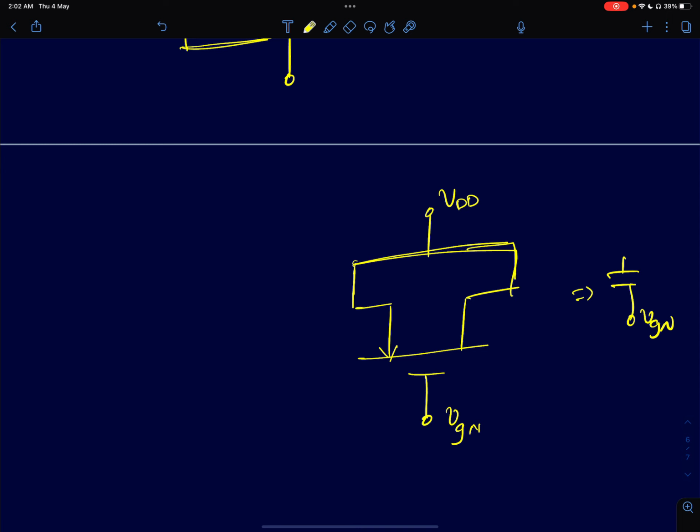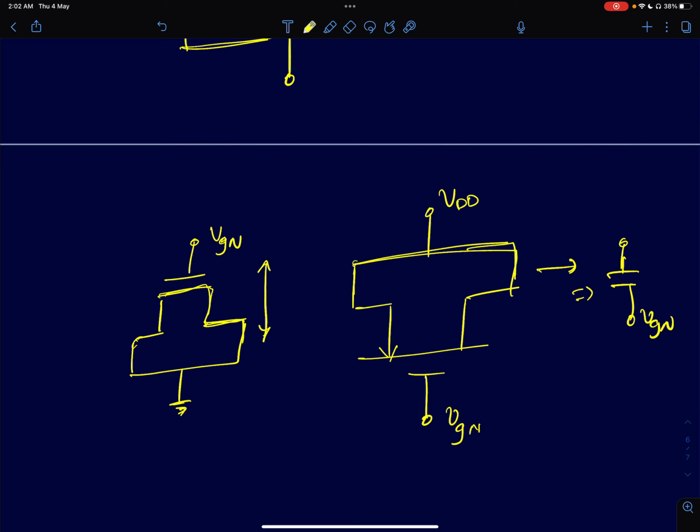So typically if you're realizing capacitors using PMOS devices, you will get what we call supply referred capacitors. If you're realizing capacitors using NMOS devices, you will typically realize it to ground. Because we normally connect bulk to ground, and since we are shorting gate, drain, source and bulk together, we would get a parallel plate capacitor, which will typically be ground referred.